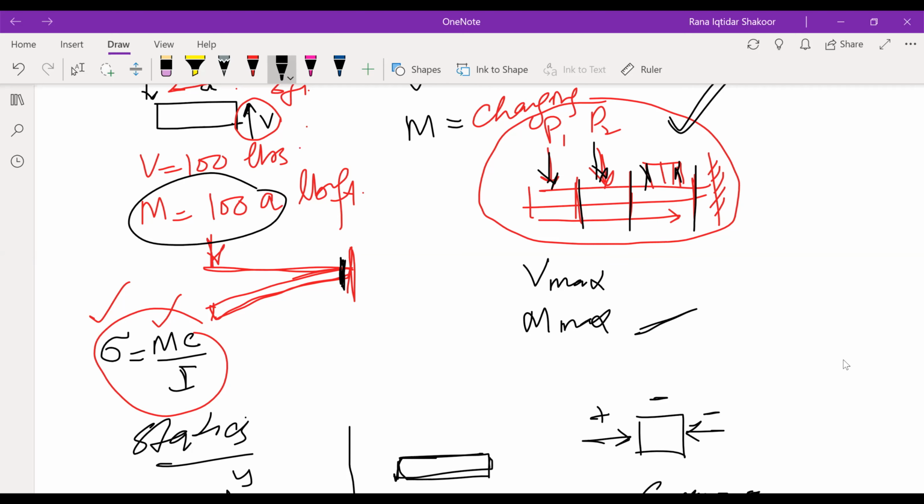So this is the particular point where the moment will be maximum, at the support, the point from where this cantilever beam is fixed. This will be the point where you have maximum moment and, resultingly, maximum stresses. So this part may be the more vulnerable part that gets into failure when a 100 pound load is applied on the tip of the cantilever beam.